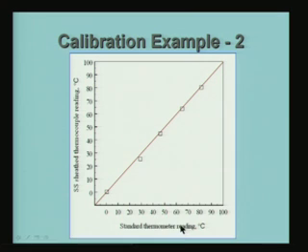That means that I have taken the reading from a handbook which gives the data for this particular type of thermocouple, and I have compared the two. That is exactly what I have done, and I am giving you the value of the voltage which is converted to the temperature, and I have plotted it here, and you can see that there are some differences, and of course, this is for a particular thermocouple.